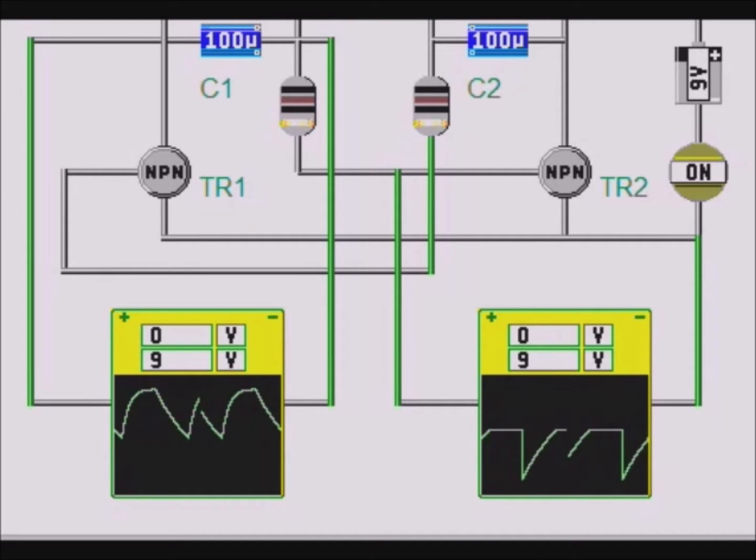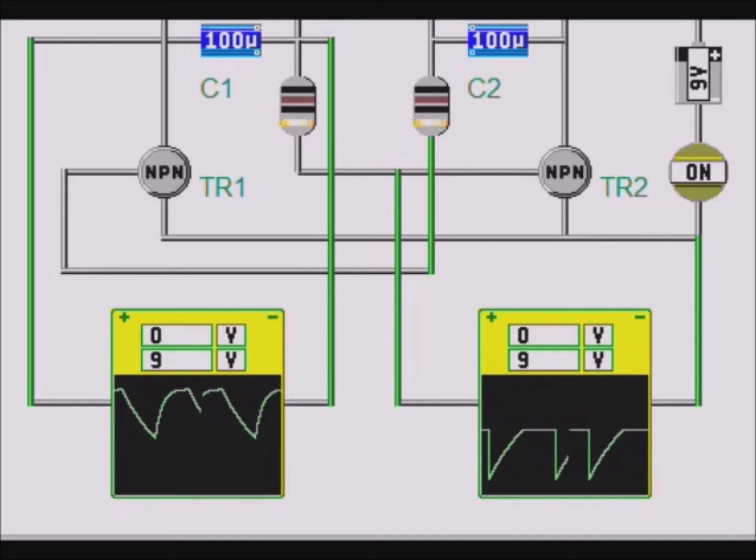The second oscilloscope shows the voltage at the base of TR2. While TR2 is off, this shows the voltage of C1, which is now like a small battery. However, it is inverted because its positive end is attached to the TR2 emitter, and the negative end is attached to the TR2 base. As C1 discharges, the voltage at the TR2 base increases until it reaches plus 0.7 volts, and TR2 turns on again, thereby turning off TR1. To understand the process fully, test the voltage and current at key points.